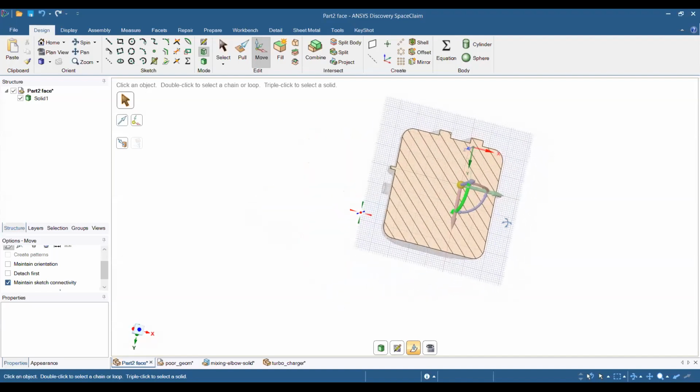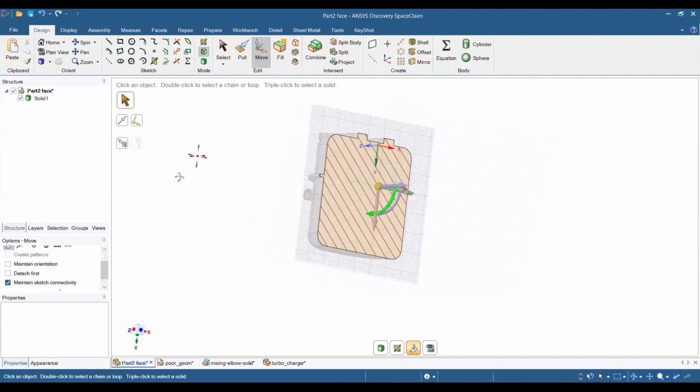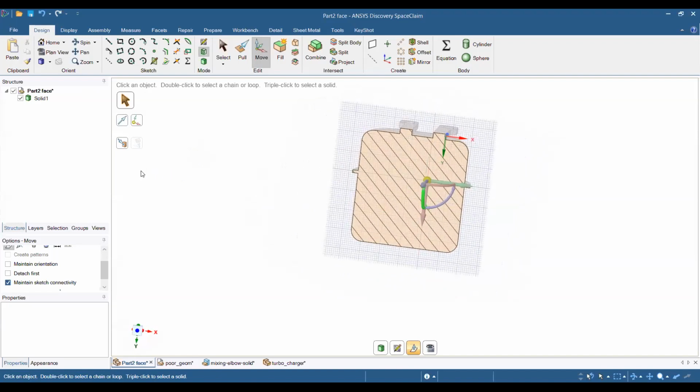Now, why am I stressing so much on the cross-sectional views? Well, because when you're trying to extract flow volumes from your geometry, it is very important to ensure that your geometry is watertight, that it does not have any leaks. And how will you check if your geometry has leaks or not? You will examine the cross-sectional views to see if there are any gaps or not, right? So it's important to know how to be able to view the cross-sections in your geometry.